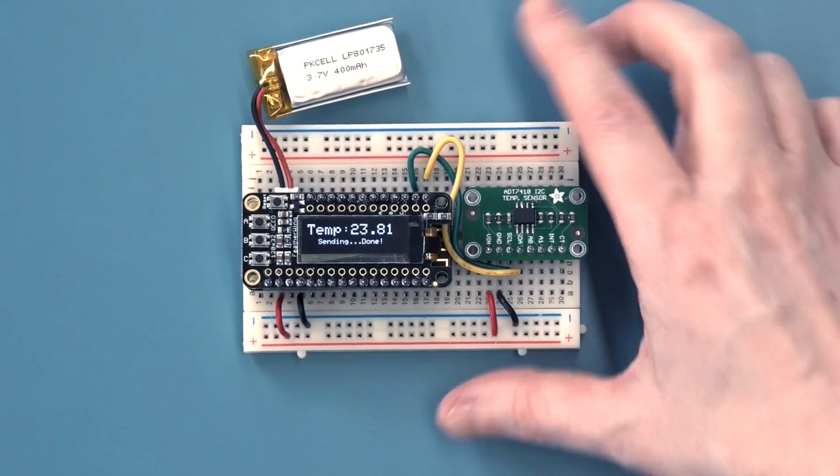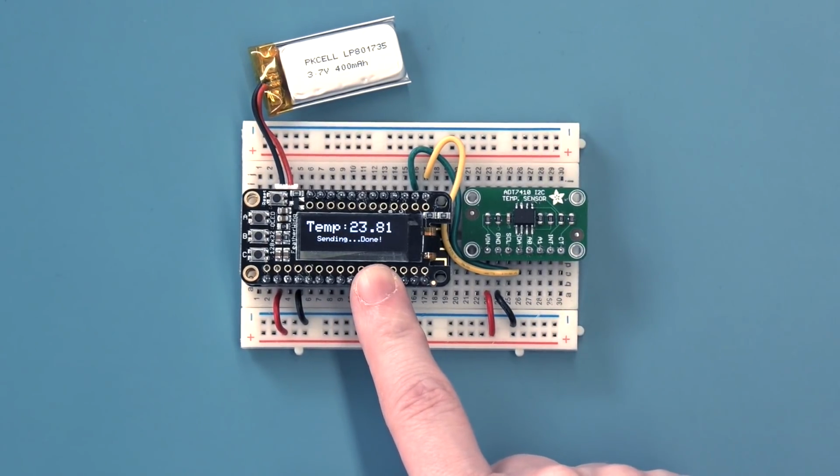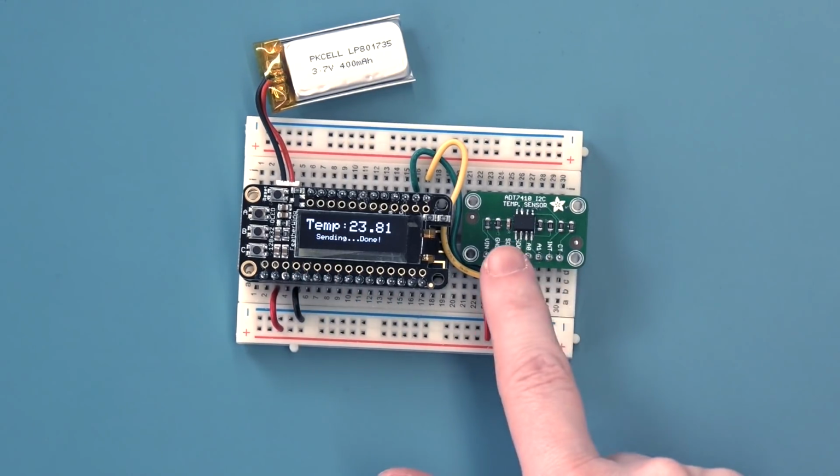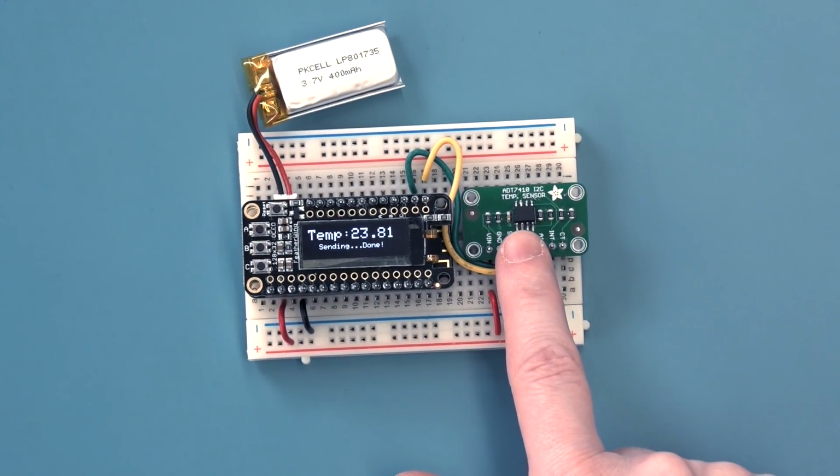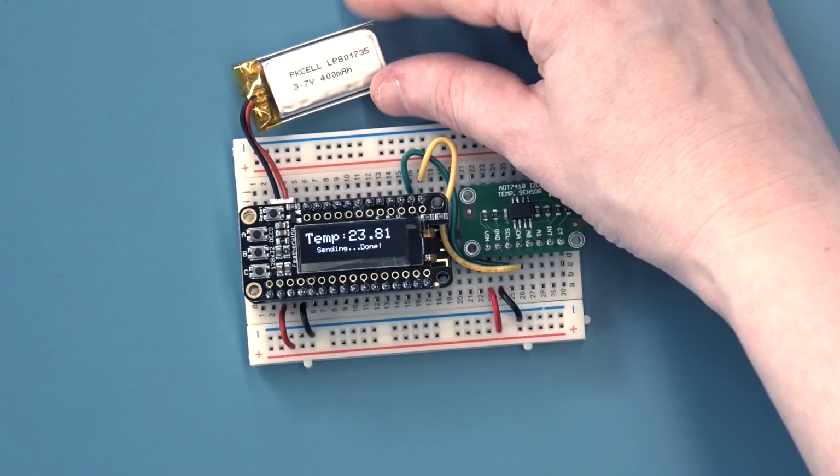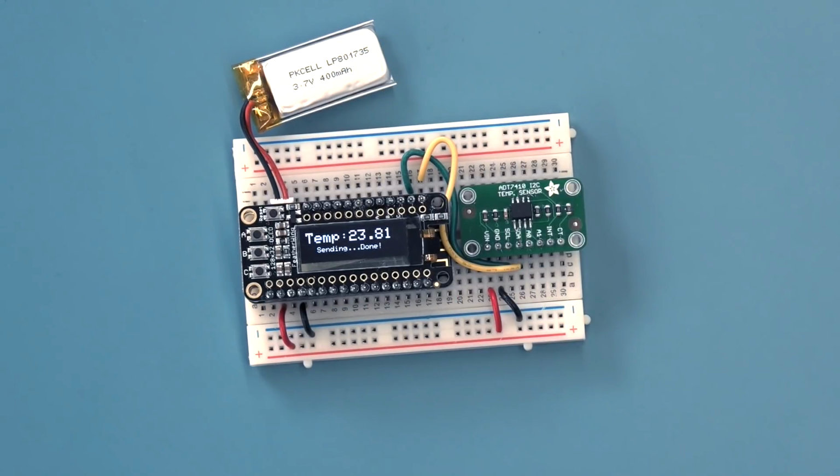Likewise, here's an example using the ESP8266 feather with an OLED on top and an Analog Devices ADT7410 wired up on a breadboard. With the ESP feather, we're stuck with a microcontroller rather than a full computer, so we don't use Python. Instead, we'll stick to Arduino C++. The trade-off is we have much lower power usage, so we can run it off a battery, and faster boot. But we also have to be more careful with memory and link management.